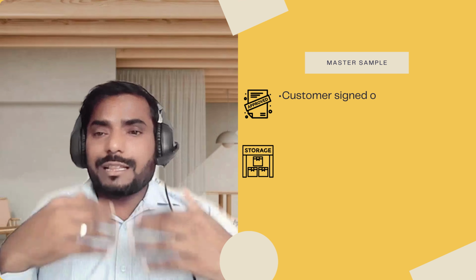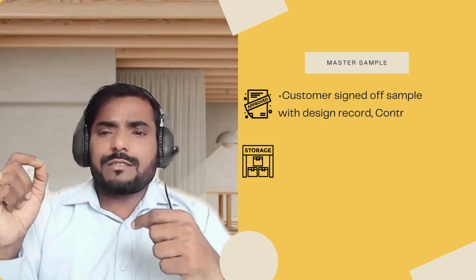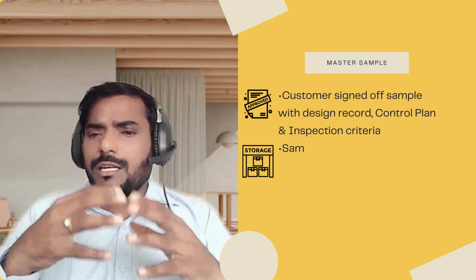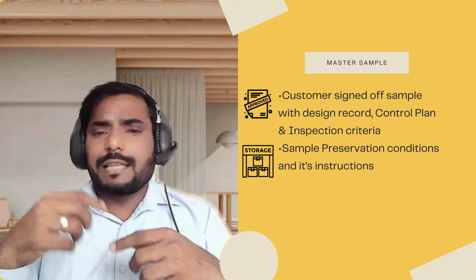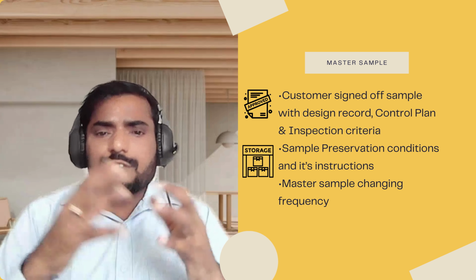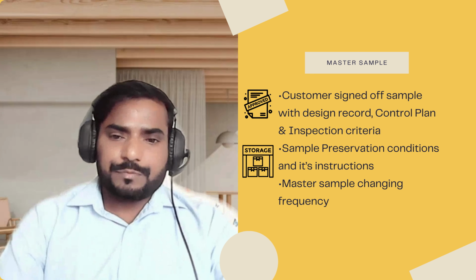So in that condition, you should have the changing frequency so that after 6 months, again you will pick one of the samples with the detailed inspection report, and you can get the approval from the customer. You can get it signed from the customer, and that component will be again considered as the master sample. So this is how you should preserve the master samples.